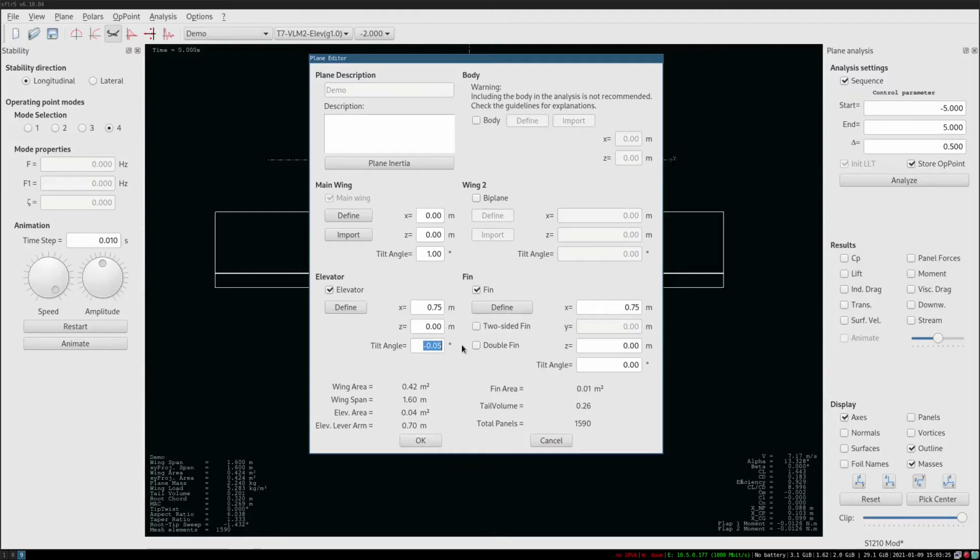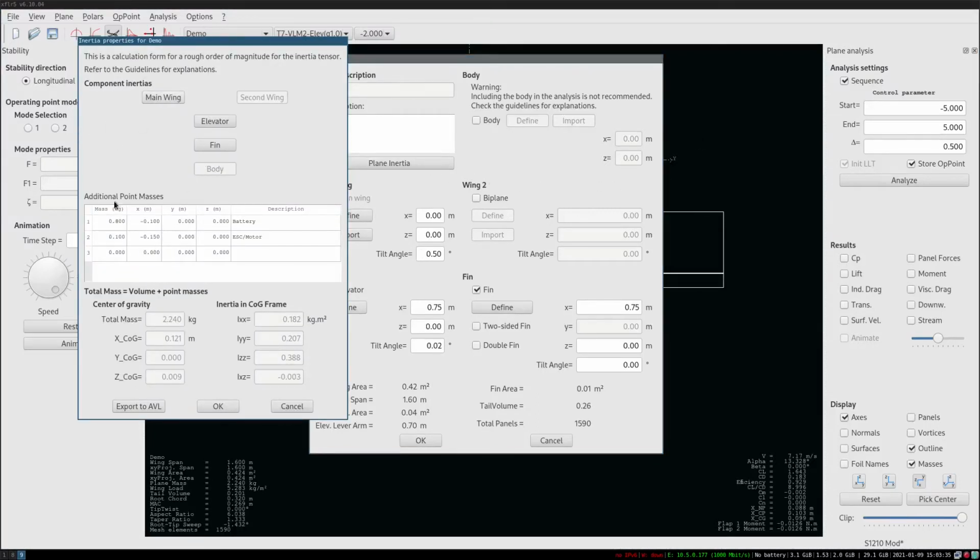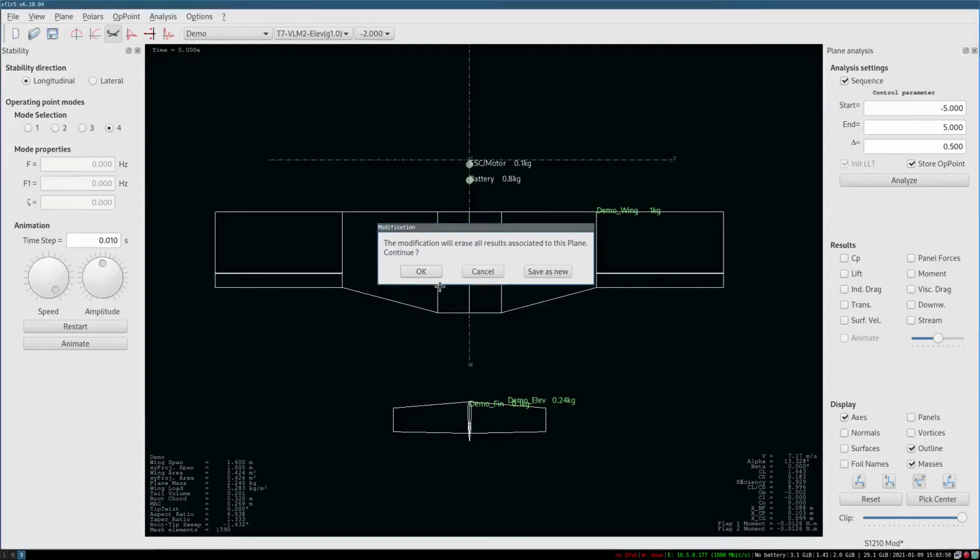No, we probably want a bit more nose down, if anything, so we'll get a bit of elevator angle on that. We will reduce our wing angle because we're quite light for the size of the wing, and we will basically try to move our battery a wee bit further forwards, and maybe add a turn to our motors correspondingly. Okay, if we do all these changes, we'll look for our changes.